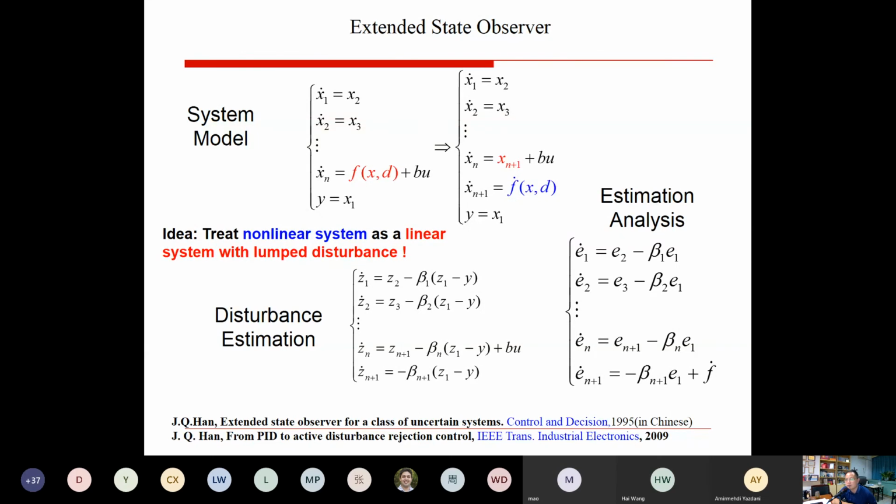Then I suggest you first need to model the system. Is it a first-order or second-order system, and what are the parameters? You need system identification. Then if the identified model is accurate, maybe you can try some model-based control method, like ADRC, DOBC, and any other model-based control method. But if you do not model it, you can't do the control design, because most of the cases are model-based.